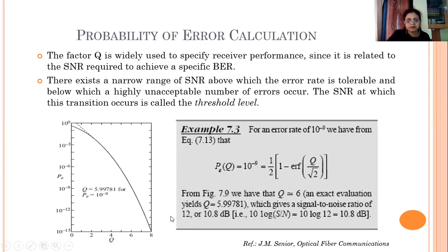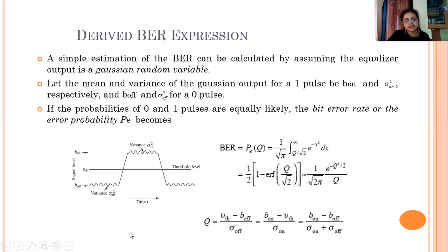So if I'm designing a quality factor in the optical communication system so that its bit error rate should be 10 raised to minus 9, or more than that, I should have a quality factor around 6. And quality factor, as I said, depends on this threshold voltage, and of course noises to certain extents are not in our hand.